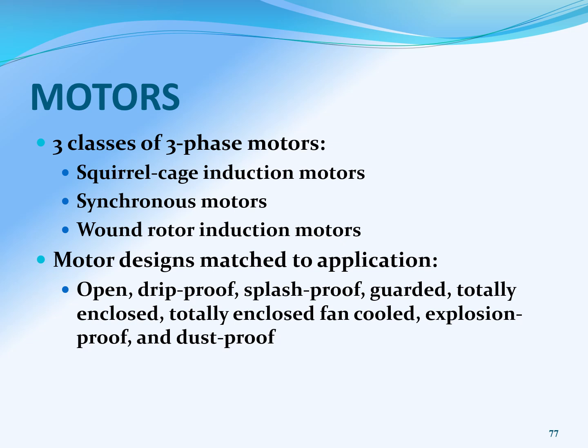Another factor to take into consideration is that there are three classes of three-phase motors: the squirrel cage, the synchronous, and the wound rotor induction motors. Depending on what it is you're trying to pump and what you're trying to accomplish, that motor design will need to match the application. As I've listed here, there are many different applications you may be trying to achieve, and what you're trying to do will dictate what class of motor you're going to need.